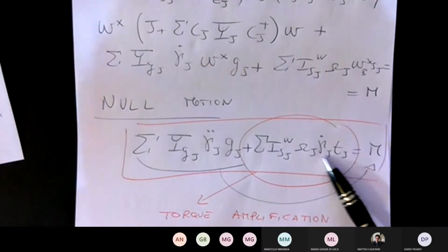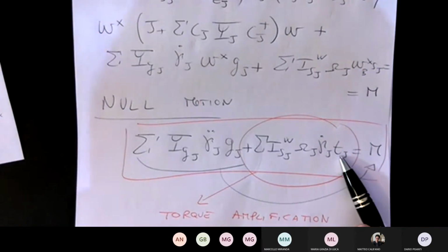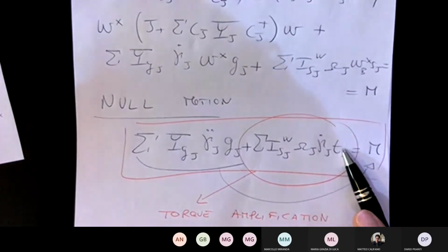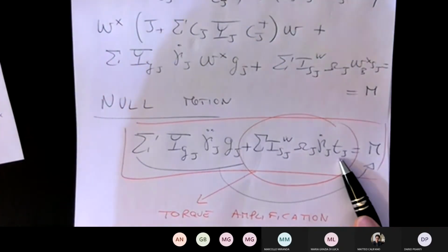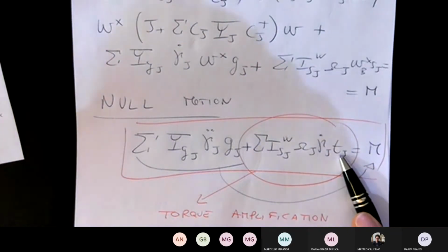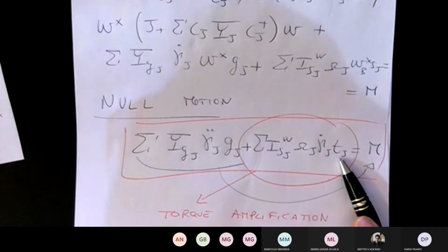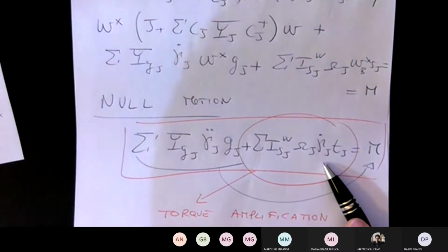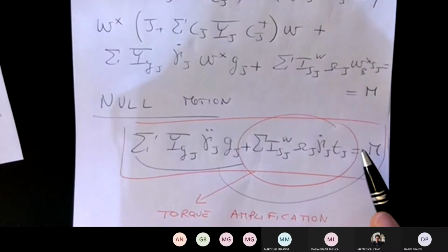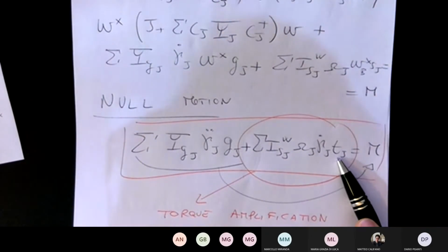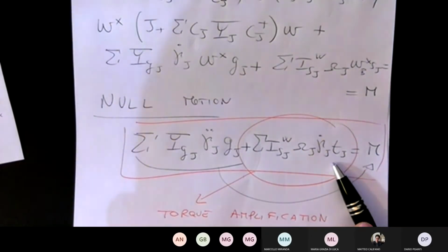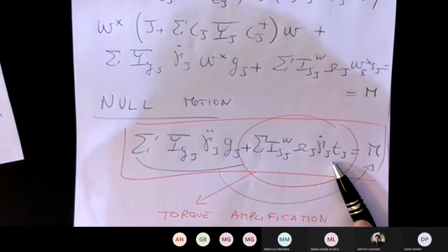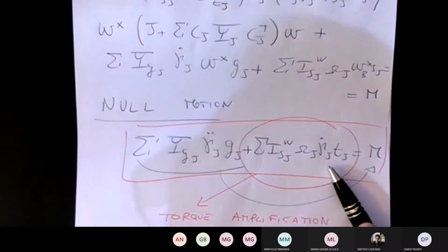So you may have a required torque that you cannot exert because you move them around throughout your maneuver, and the t-axes end up in a configuration that is called singular. In fact, there are control laws that try to avoid that. While you're controlling orientation, performing a slewing maneuver, whatever it is, you also keep an eye on not ever making T's parallel to each other, for example.